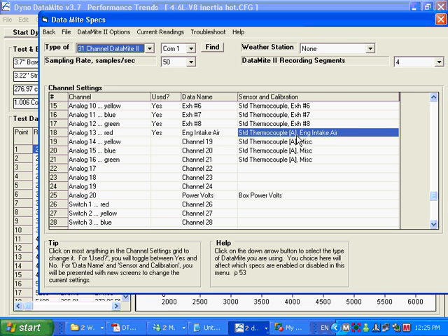So if you need critical comparisons like this cam versus this cam, don't run this cam today and cam B a week from today. Try and get them all on the same day, and ideally, if it's a critical comparison, you want to run cam A, cam B, and go back to cam A, and ideally go back to cam B, because just pulling the engine apart and putting it back together can change things.